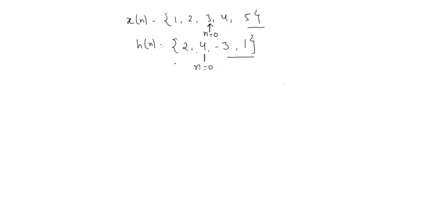Before doing the circular convolution of these two signals, since you have to find the 5-point DFT, because the next number is 5, first of all you have to make both vectors start from n equals 0. If it is not there, you have to make it. How will you make it? Just shift it. 3 is the first one, so I'll write 3 in the first place, then 4 and 5. Now the first two I can bring here, because anyhow I have to circularly shift these vectors in the matrix form, which is the short trick I told you.